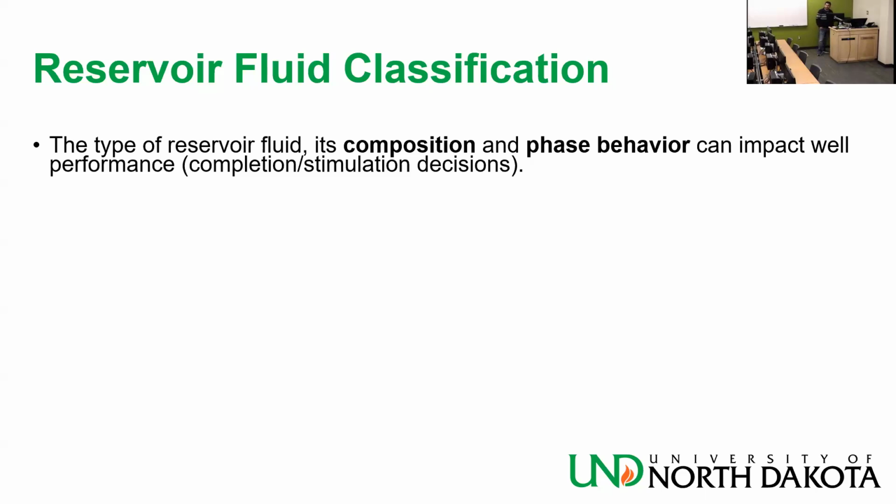H2S is crazy. You cannot see it. It's colorless and odorless. And it can be detrimental in very, very small quantities. So please take it seriously if you are in the field and you have H2S trouble. We all have to wear our H2S monitor, which is a yellow one.